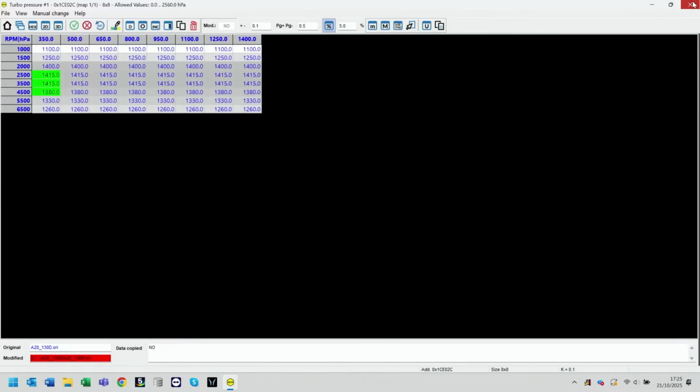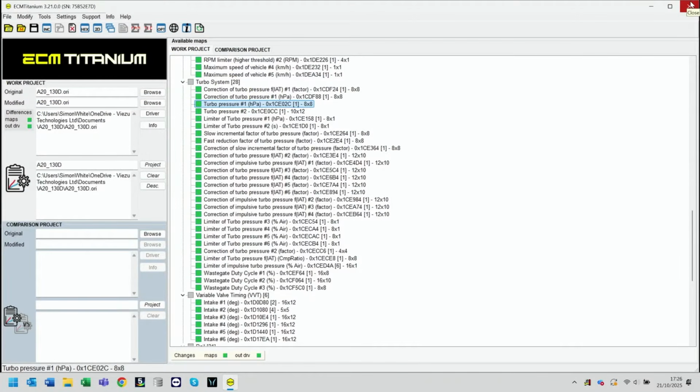With data logging and time on the dyno, of course, we could look to do that as we have slightly higher values in this table. But staying on focus for what we're trying to achieve here is a nice, safe, smooth and progressive stage 1 performance tune using the values inside of the ECU itself. So that validates that we can push to that 190 nice and safe.